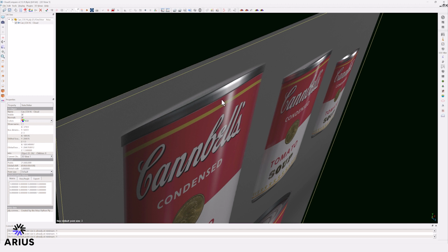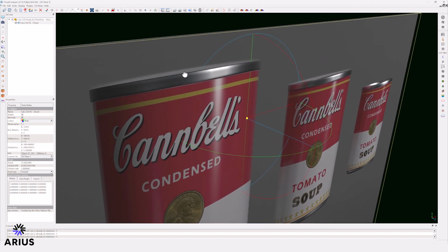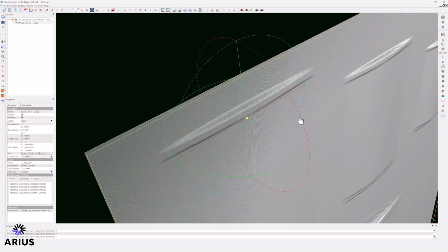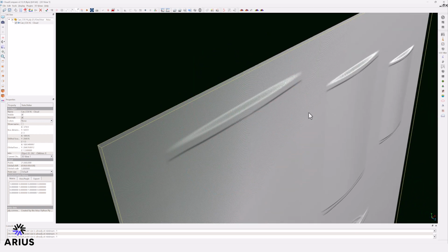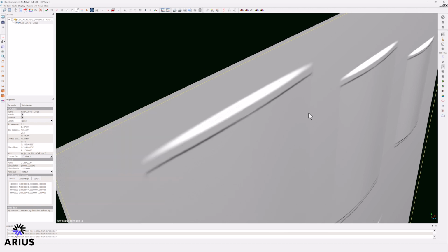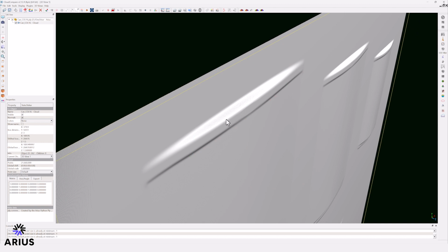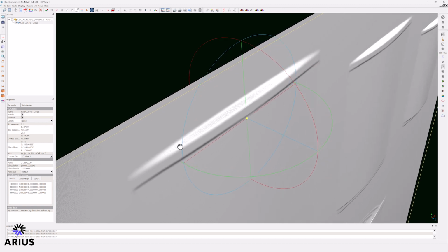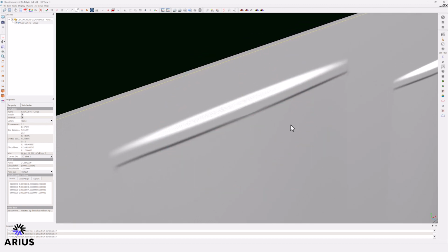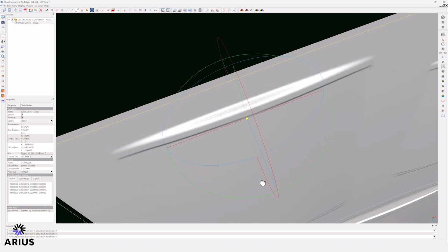If you can see through to the empty world space, then it's possible the print will have a darkening of the color. Zoom in with the mouse wheel and then adjust the point size by holding Alt and the mouse wheel. Adjust the point size until the flat areas appear solid. The areas here with the dark gaps mean there will be less ink landing on the slope, and therefore some of the dark base color underneath showing through. The larger the gaps, the more likely the color will print darker, but it doesn't need to be completely solid.